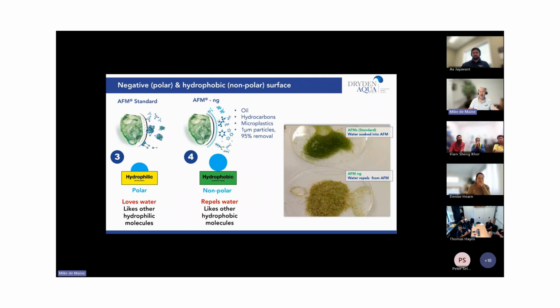In other applications like animals, aquariums or aquaculture, we actually put in a drop of dishwashing liquid, and that breaks the surface tension, allows the media to settle very quickly, and then they can put it straight into filtration mode or backwash it. But in aquariums and aquaculture, most people don't want to add drops of dishwashing liquid into their filters.